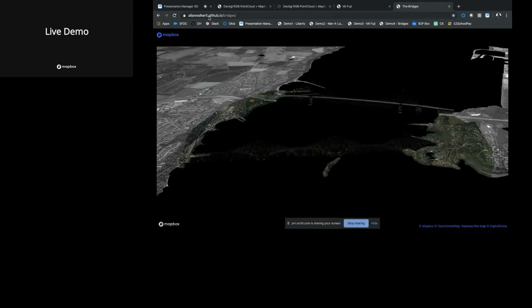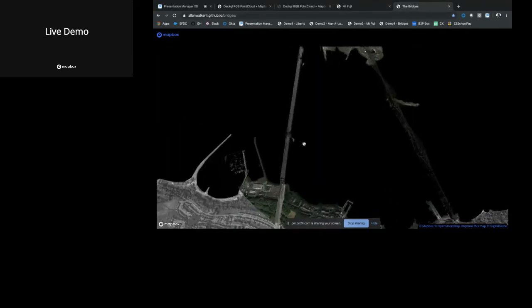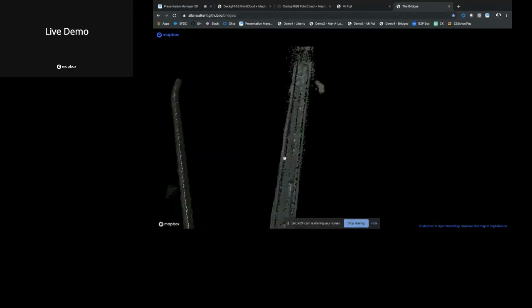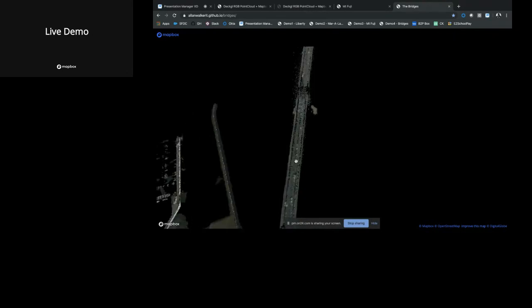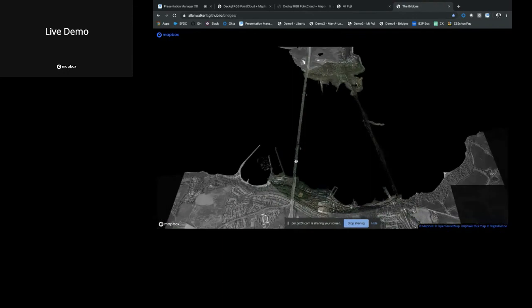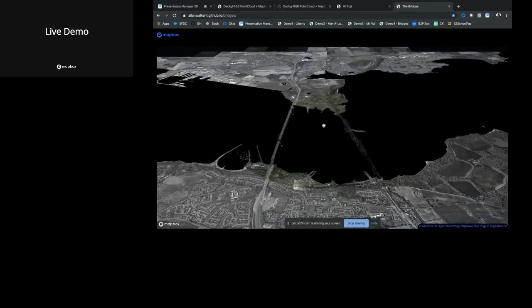So for example, if you've got LIDAR data that goes back to 2014, the image that you drape on top of it might be of the same vintage. It might be later, it might be earlier, and therefore some things to note, like for this bridges example, if I zoom in, these car positions are from the image rather than from the actual LIDAR data. So it's just something to note that when you're performing this kind of analysis, synchronizing the elevation data with the actual image is definitely a consideration.